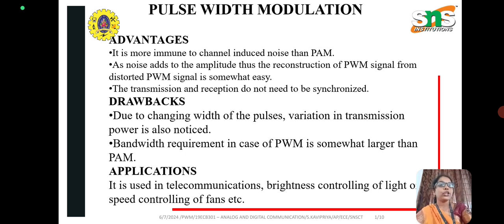A drawback is that due to the changing width of the pulses, variation in the transmission power is also noticed. Second, the bandwidth requirement in pulse width modulation is somewhat larger than in pulse amplitude modulation.